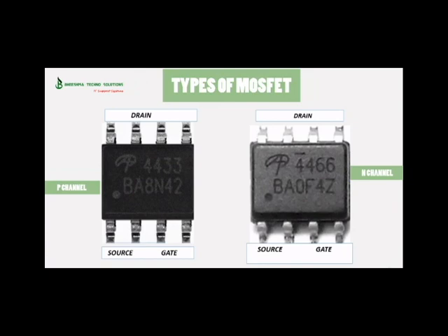Actually, the laptop motherboard applies mostly N-channel MOSFETs. We can see lots of N-channel MOSFETs on the motherboard. Only this P-channel MOSFET has a role in the 19 volt and discharging sections.